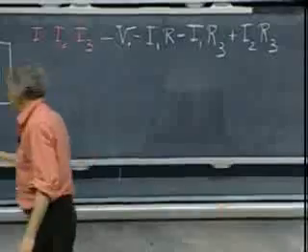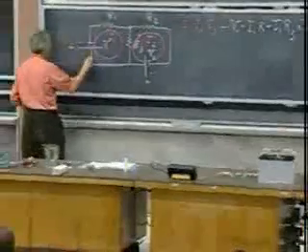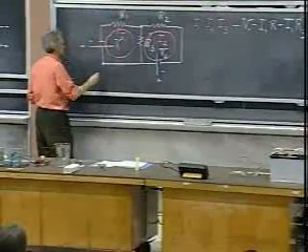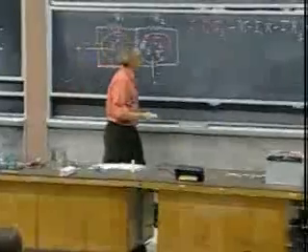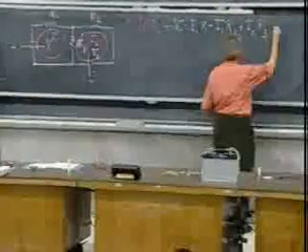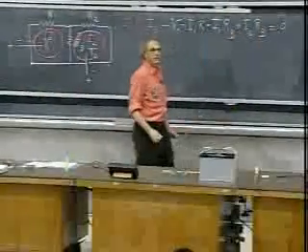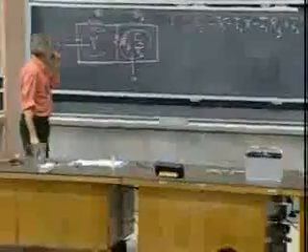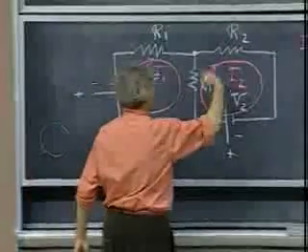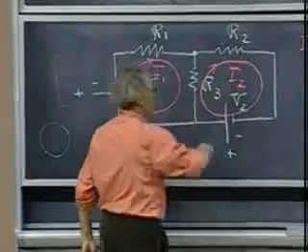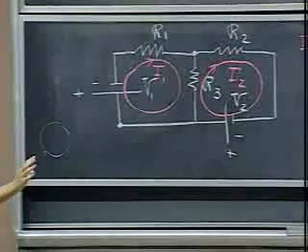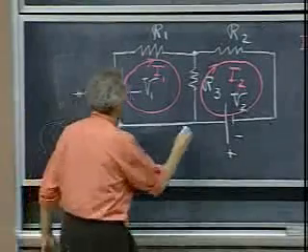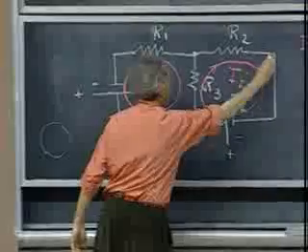Now I'm back where I was, because these wires have no resistance. And so I'm back where I am, so this is 0. One equation with two unknowns, I1 and I2. So now let's go around this one. We can go clockwise, we can go counterclockwise, makes no difference. Let's start here, and I go in this direction once around.